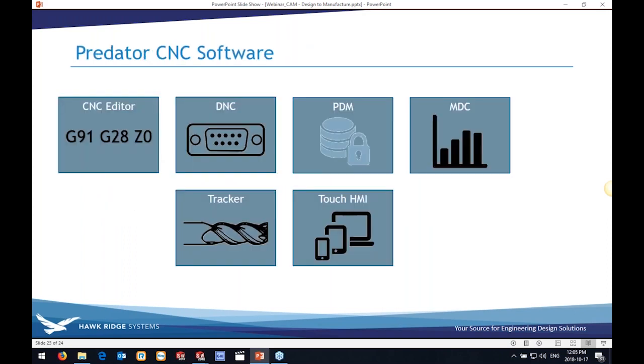But essentially what it allows you to do is collect data from the machine to say, okay, when did the operator push cycle start? When did the operator basically run it into setup mode and things like that? And he can have a little tablet, or he can have a screen or a computer at his station that goes, okay, I'm now in setup. He hits that button, or he scans a barcode and it reads all the data into the software, so he knows exactly what he's programming at any one time. All of that can actually be fed back into Predator, so that you can tell what the live tool data is, what the data is coming off the machines.